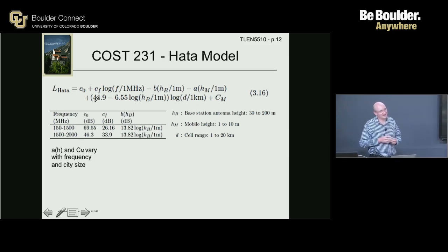What did they measure exactly? Because the first model came up in 1968, right? So in 1968, there was not a lot of activity when it came to cellular. Oh, yes. That was all Okumura's measurements. It was continuous wave throughout the city of Tokyo. They had a transmitter and they measured things everywhere. And then they changed the frequency and saw what happened.